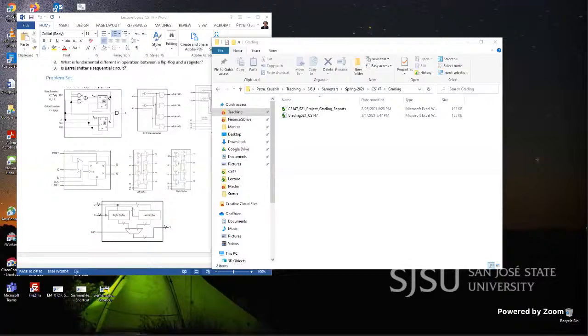So here we are talking about 4-bit, but the configuration is the same. It's a 4-bit right shifter and a 4-bit left shifter. We have a multiplexer to select between 2 inputs, like a 2x1 4-bit multiplexer with a selection control, whether left shift or right shift, on the result part. But the detailed explanation lies in the implementation of the connections between the muxes. So it's a 4-bit shifting.